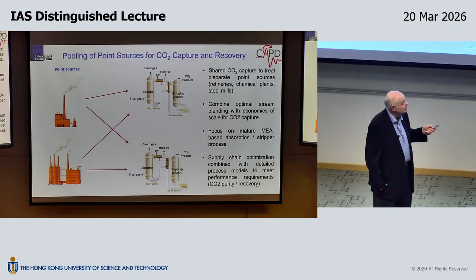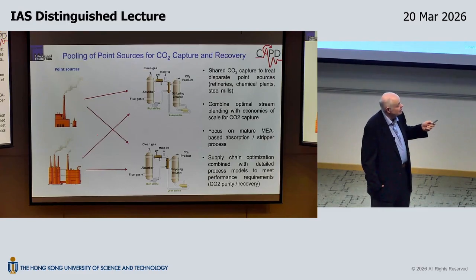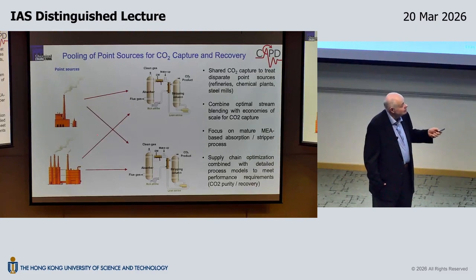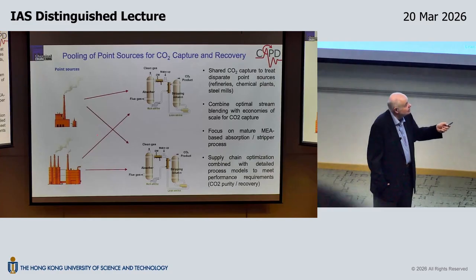We have an absorber with a certain amine scrubber, which is basically something like MEA, monoethanolamine, that we're going to use. And we're going to have a stripping column that regenerates the CO2 captured by the rich amine, and then separates the CO2 from everything else. The lean amine that's left goes back into the absorber and runs again.